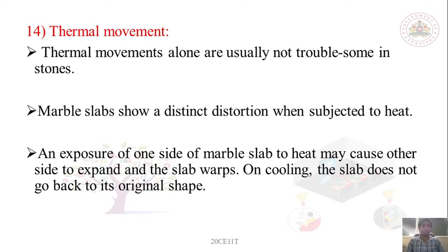If you are using a kitchen slab, there is a chance of thermal heat exchange. Then you have to use other materials like granite slabs or even kadapa slabs, but not the marble slab, because marble can warp, change its shape, when it is applied with a certain quantity of heat. If you have a good burner and good spacing between the stove and the slab, then that may not be the problem. But in kitchen slabs, you may not use marble slabs because it can easily warp.